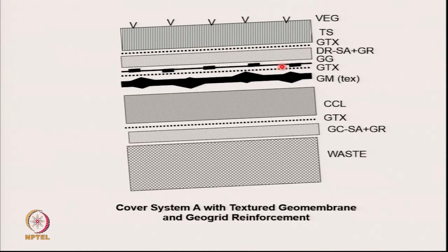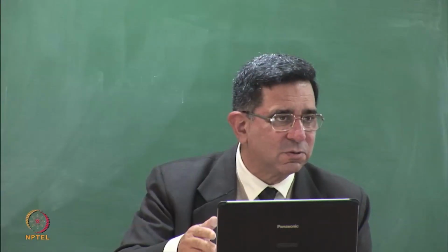I have a big problem. The sand is 1 foot thick. It's too heavy. And W cos alpha, you remember, the downward force is pretty high. You've done slope stability, you're doing slope stability. Look at it as slope stability of infinite slopes.